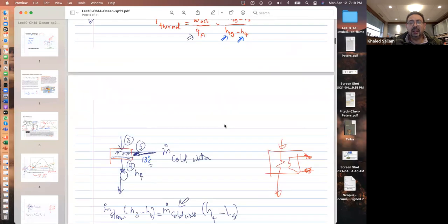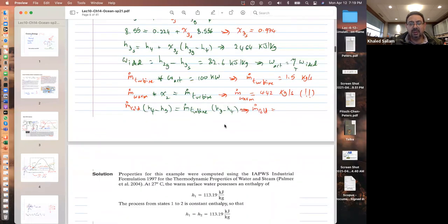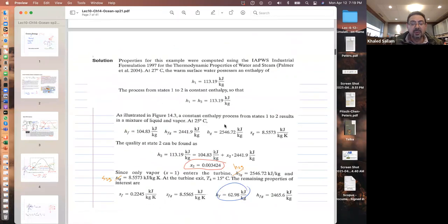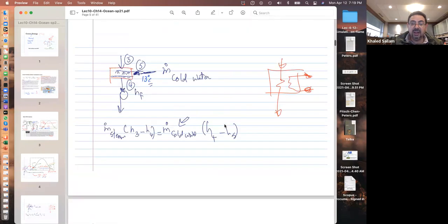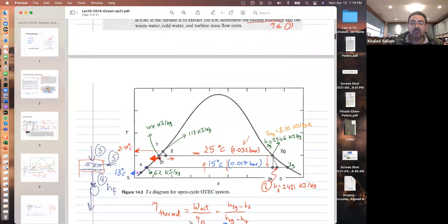And so we did this example, and you guys had a homework about doing those calculations at different pressures or even different configurations. I just want to say how this design is really cool in something, and that is the water that you're sending from here, sorry, not this one, this one, is clean water, meaning it's not salty water. When we flash it, that vapor comes, but the remainder is a little bit even more salty, because we took some vapor from it. But the rest that went through the turbine and expanded is clean water. So people can drink it, right?